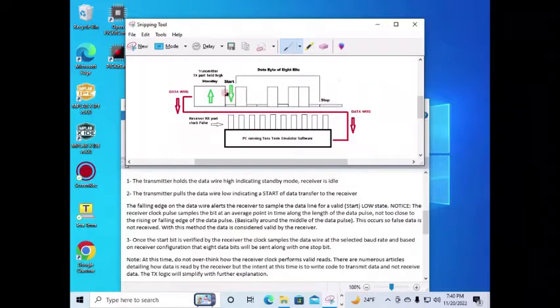When the emulator sees the start of a data transfer, it knows that it's going to be receiving 8 data bits, and then one stop bit, and it'll know that that's the end of the data transfer. Sometimes emulators can be set up for more bits, maybe 10 bits, and so on. Then it would expect that many bits, but for this presentation it's expecting 8 bits and then one stop bit.